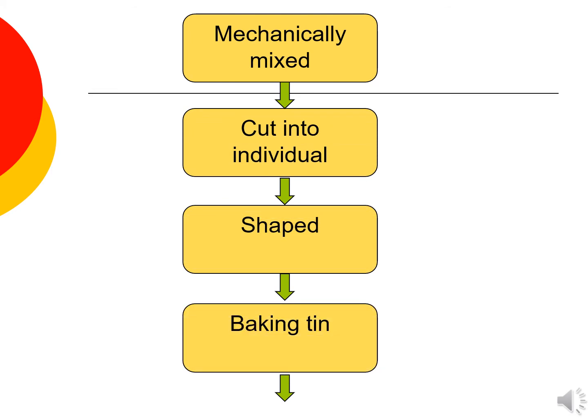Flour, water, yeast, salt, fat, and minor ingredients such as vitamin C, emulsifiers, and enzymes are mechanically mixed for about 3 minutes. The high shear mixing generates high temperatures in the dough, which is cooled in some advanced mixers using a cooling jacket. Chilled water or ice may also be used to counteract the temperature rise during high speed mixing.